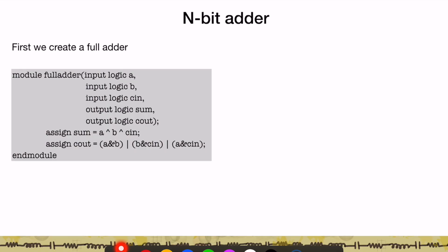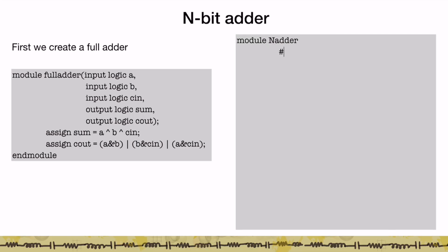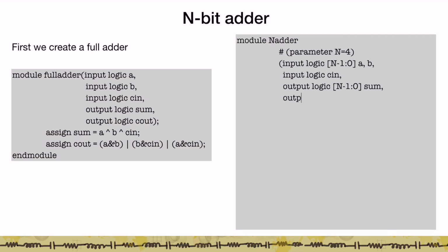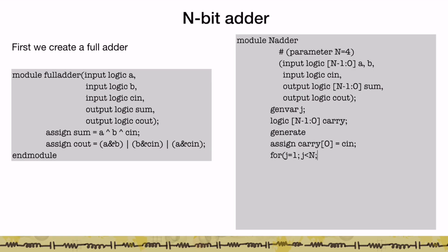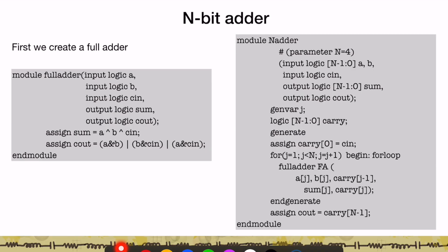And what I now want to do is cascade. This is a very simple ripple carry adder where I add the LSBs, push the carry to the next significant bit, and so on. The way I would write this is by parameterizing the code. I'm creating an n-bit adder, where the parameter by default is set to 4, and I'm defining 2 input words.